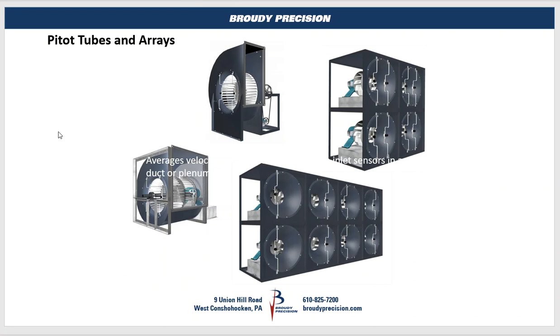On this slide, we see the different forms of fan inlet measuring pitot tubes. And you will see that there are averaging types, which go across the inlet of the squirrel cage, as shown here. You also have them on the inlet of the bell of a fan array, and these are typically averaged together so that they're all commoned up.